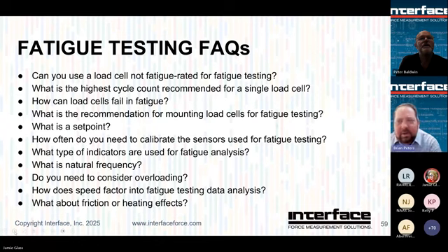Do you need to consider overloading? How would you answer that? Absolutely. Yeah, so not only from the extraneous loads, like we've really beat with a stick here, but also overload your test article. What happens when that thing fails? Are you okay with writing off the rest of your test stand, or do you want to take some precautions to ensure that everything else outside of your DUT is in good working order after you go to failure?